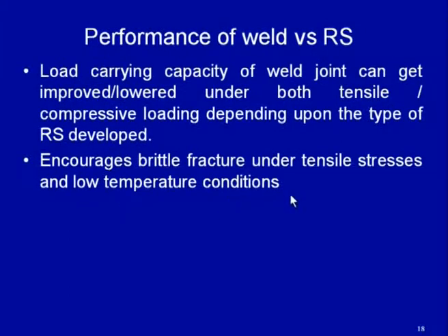Further, the presence of these residual stresses encourages brittle fracture under tensile stress conditions, especially under tensile stresses and low temperature conditions. So, if residual stresses are present in the weld joint, then these will promote brittle fracture under tensile stress and low temperature conditions.